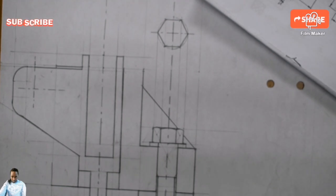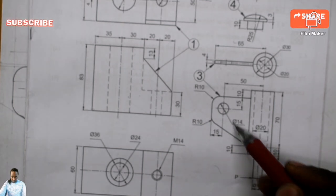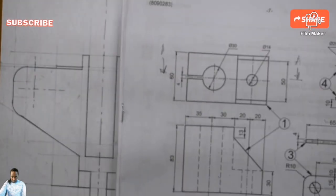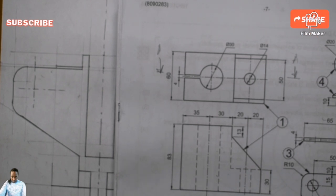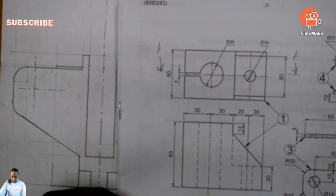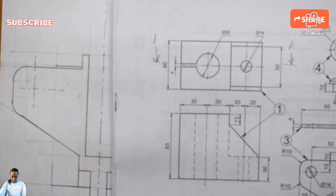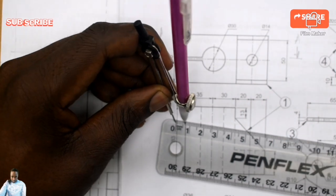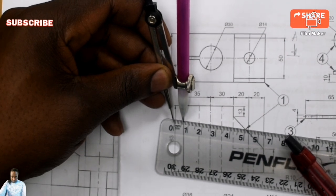So now I can draw this hole, diameter 14, right there. You place your drawing compass here, you open it to the half of 14. So 14 divided by 2 is 7 millimeter, isn't it? So you take a drawing compass and open it to 7 millimeter. If you have a stencil ruler, it's going to be fast and quick for you to understand. So you open it to 7 millimeter.